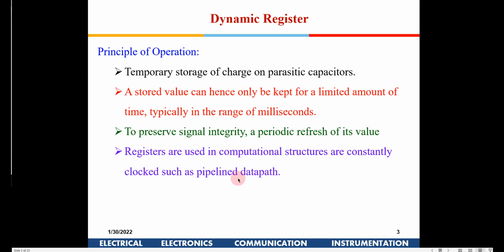What are they doing? They are just fetching the instructions from the memory bank and storing them temporarily for execution. Instead of waiting for the present execution to complete and then fetching data, a pipeline microprocessor prefetches the next instruction, decodes it and keeps it in the instruction queue, right?